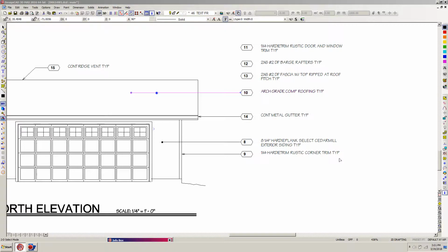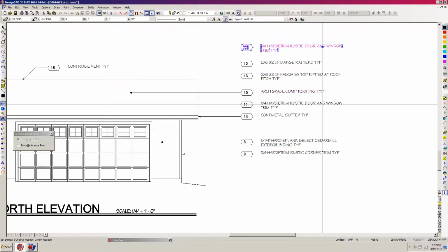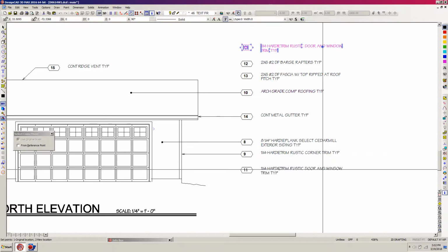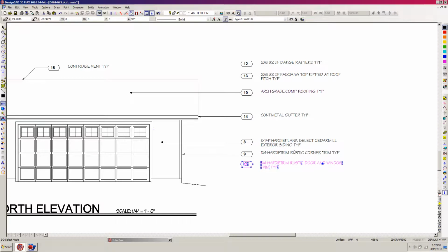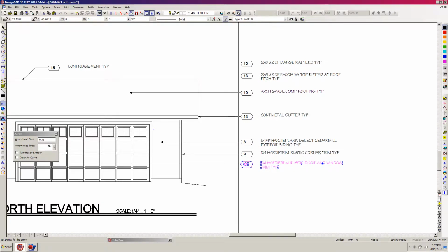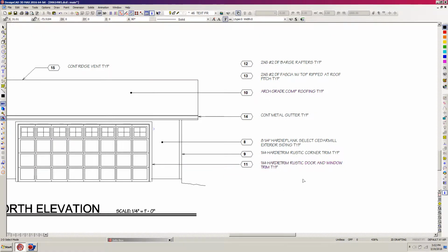Okay, so now we have to deal with our barge rafters and fascia, and we also have to deal with our actual door trim, which is also going to be 1x4. So I'm selecting the door trim, and I'm just going to move that on down, gravity move to the handle, M for move, and arrow it on down like so, about like there. Set a point, and then arrow, H for orthogonal mode, and then K to the trim, snaps to the trim, and hit escape.